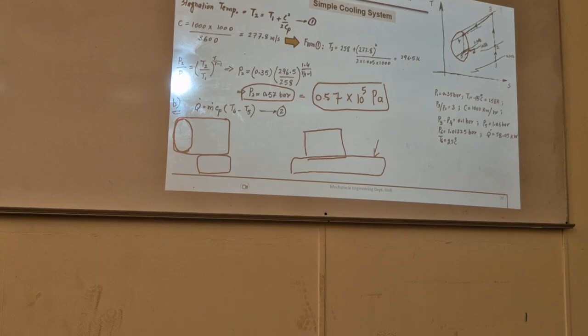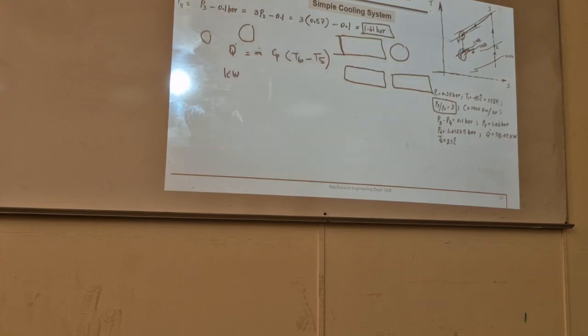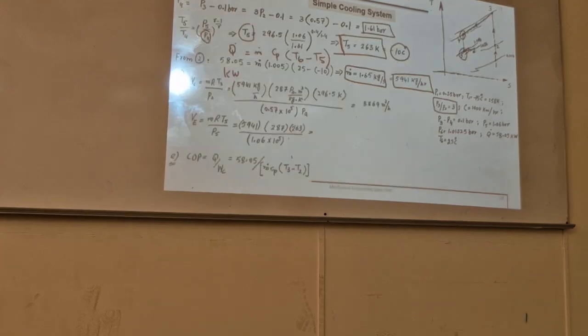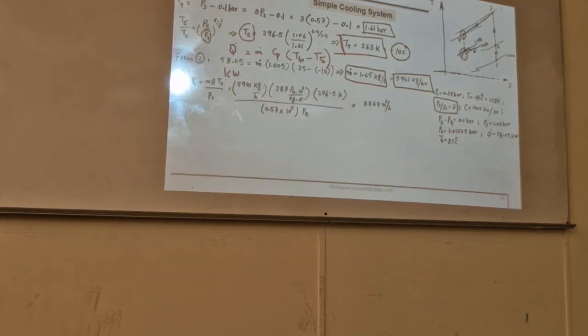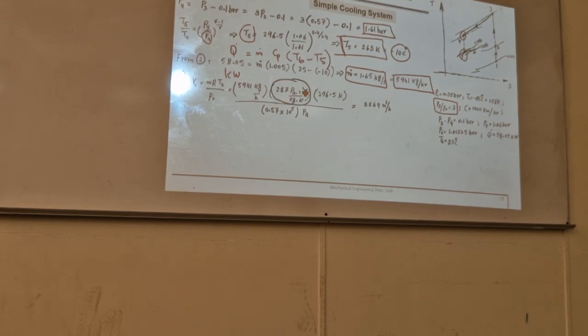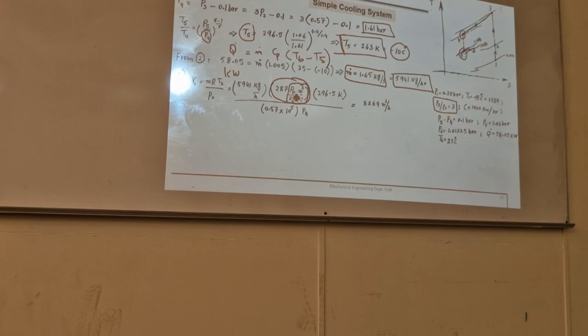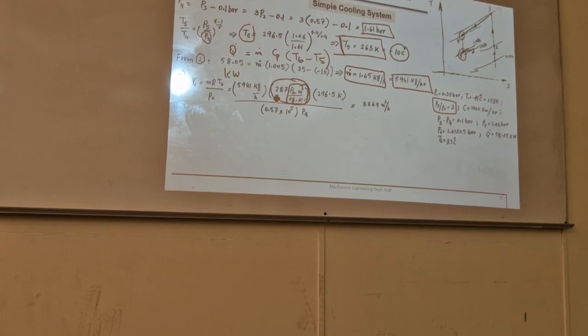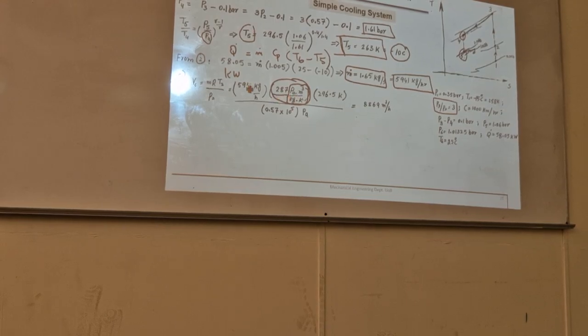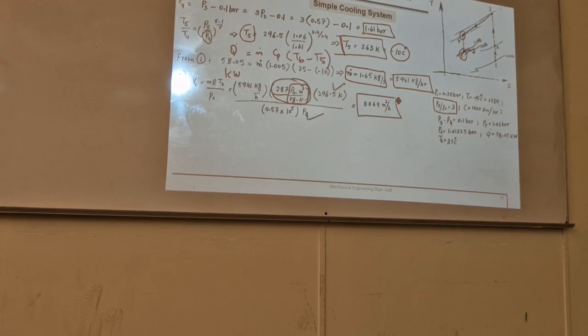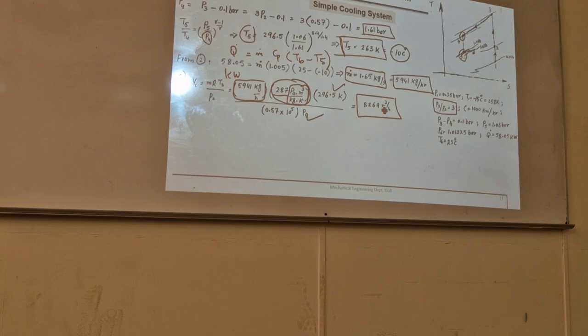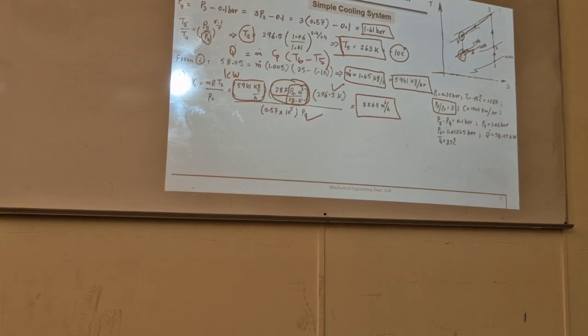So if you are using pascals, then R for air will be 287, not 0.287. The units of pressure in this R is pascal, so that's why 287. So m dot R T2 you already calculated, P2 known, so here is the volume handled. Because mass flow rate you are taking in kilograms per hour, the answer is meter cubes per hour.